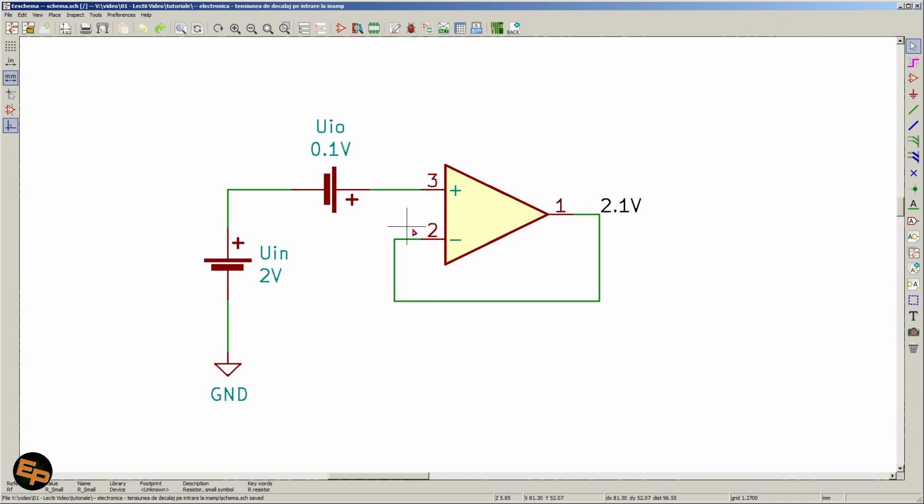It's a byproduct of the fabrication process, and it's not something that any manufacturer can remove completely. It's just something that they can do better, but this difference in voltages is going to be present no matter what. So we can see this difference in voltages as an extra voltage in series with our desired signal on one of the inputs.